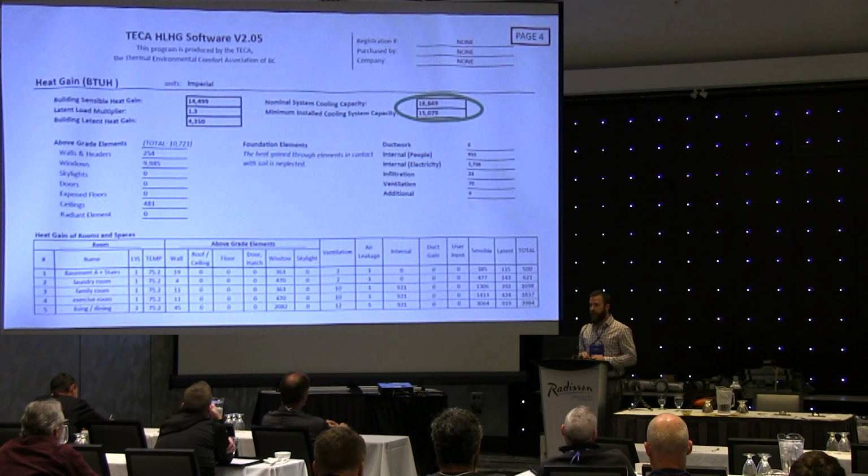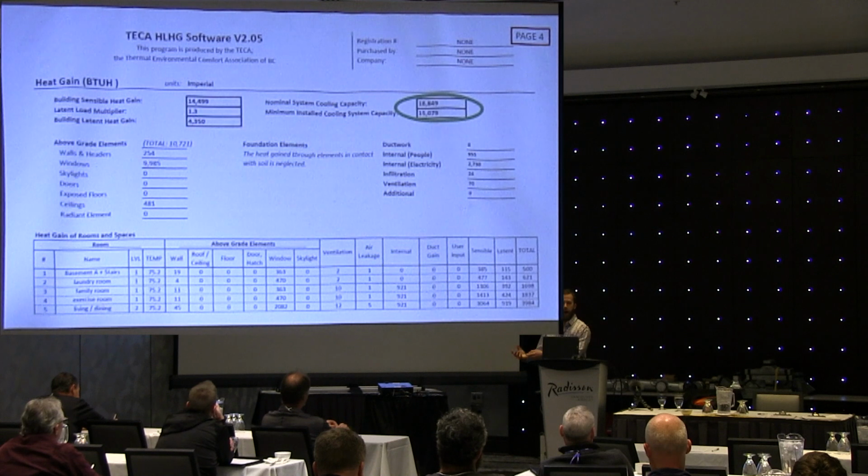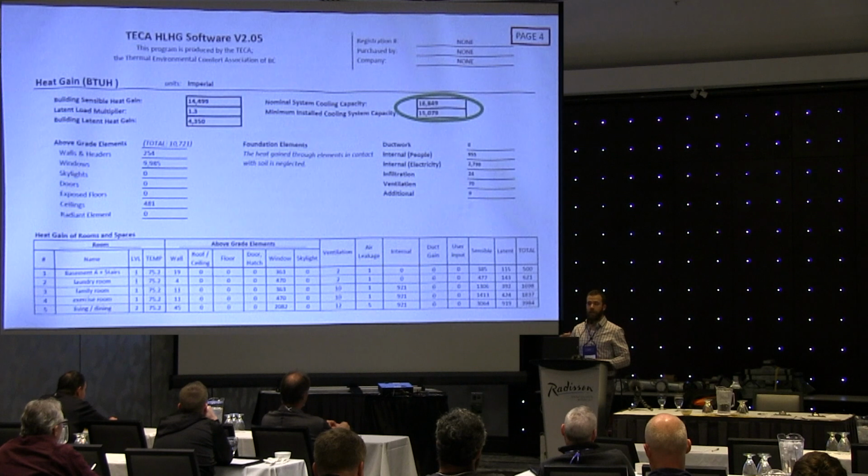So sensible heat is the temperature of air in a room. That's sensible heat, right? When I heat air up from 20 degrees to 50 degrees, that's a change in the sensible heat. I've added sensible heat to it. When I take ice at negative 10 degrees and I heat that block of ice up to 0 degrees, that's sensible heat because it's changing temperature.